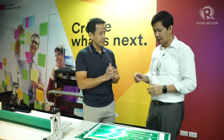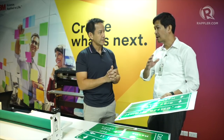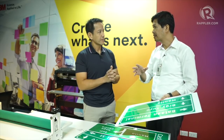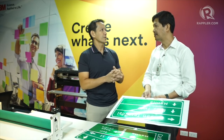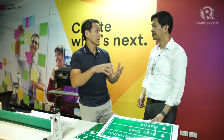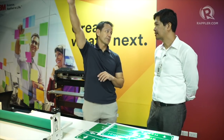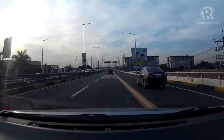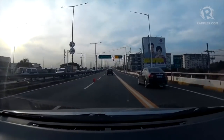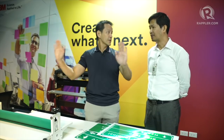Again, to add to that, when you say placement, for faster roads or roads with 3 or more lanes, it's better to have the signs put overhead. So this is what we see sometimes in highways, where the sign isn't on the side of the road, but actually overhead. Yes, and that's so that it's visible from further distances. Because if a sign is on the side of the road, it can be blocked by vehicles next to it. Lorries, trucks, yes.